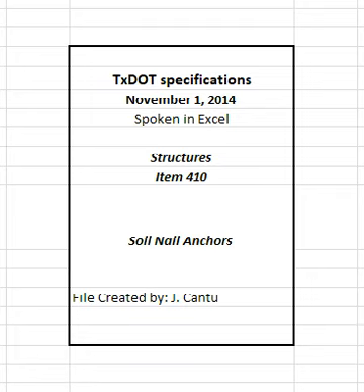The total measured movement at the maximum test load exceeds 80% of the theoretical elastic elongation of the unbonded length of the test nail, and a pull-out limit state does not occur for the verification load listed on the plans. Pull-out limit state is defined at a load level at which the test load cannot be further increased while there is continued movement of the test nail.